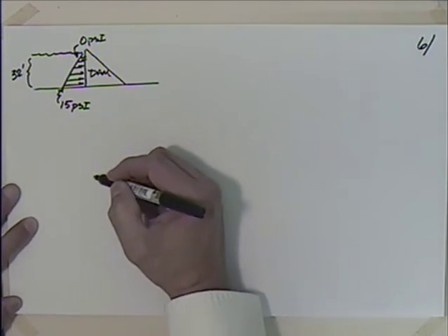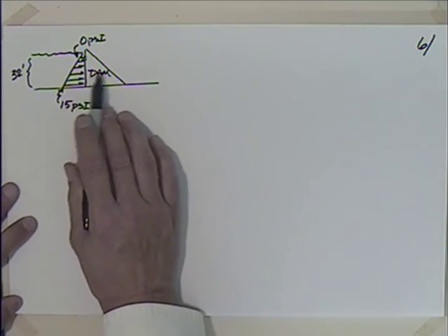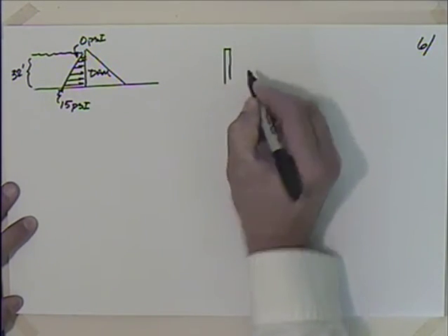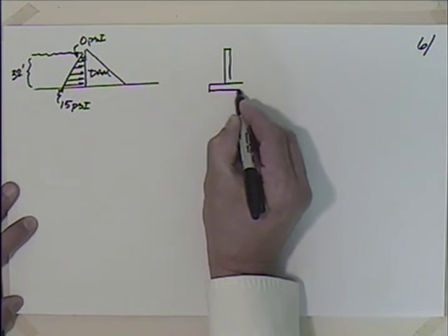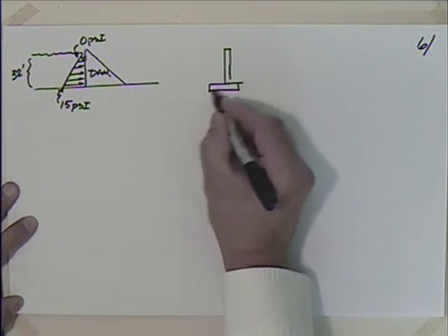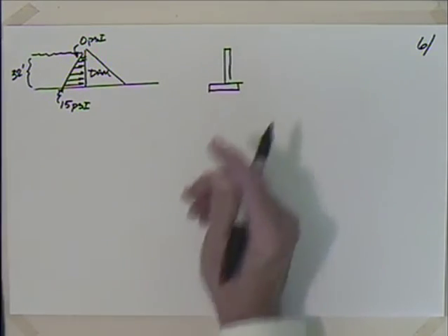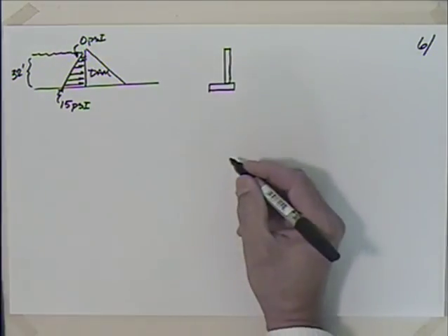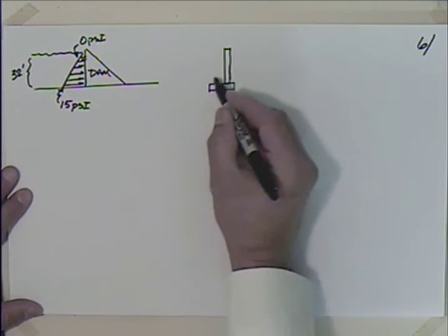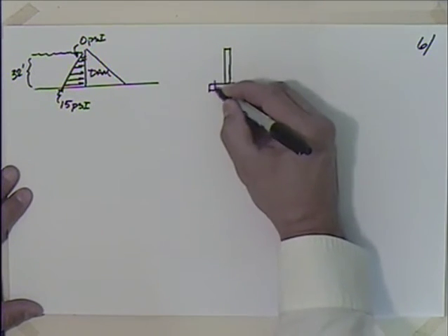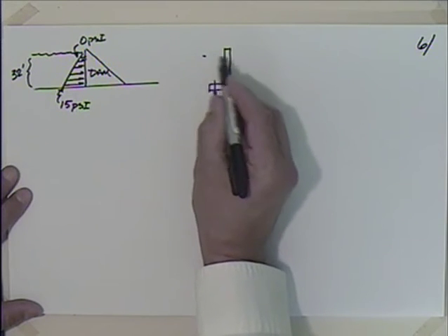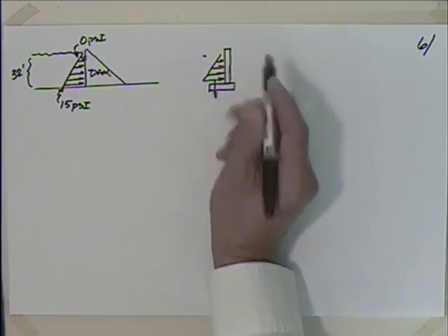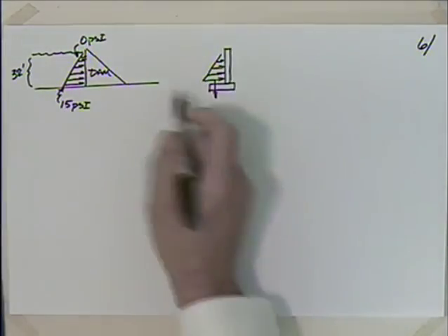So let me take this pressure distribution, and incidentally, the civil engineers that go on to do earthwork and whatnot, when you look at that retaining wall that we saw at the beginning of lecture there, this is the heel and the toe. Usually the heel's a little bit longer, like that, if you have the space. Because you've got the weight of the soil acting down there, holding that and resisting this pressure distribution here. That's probably going to look something like that, right?